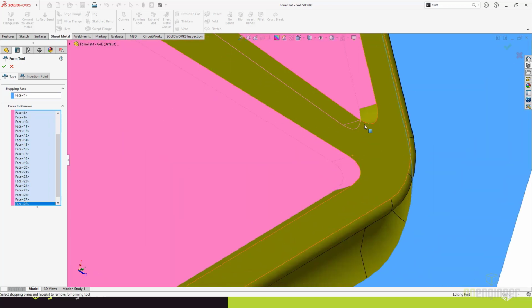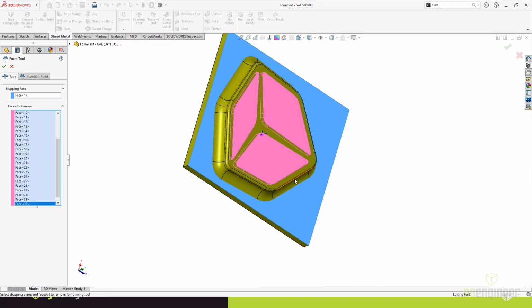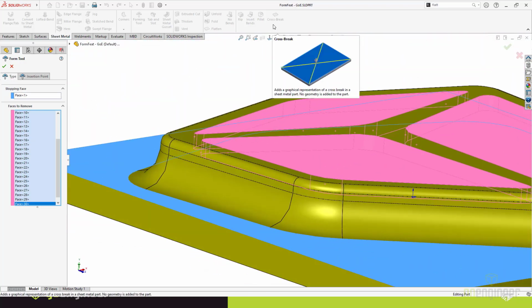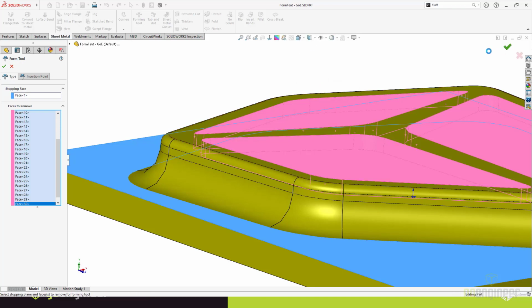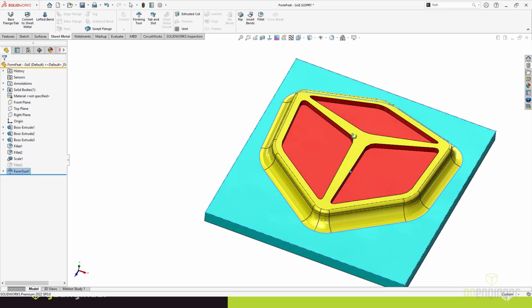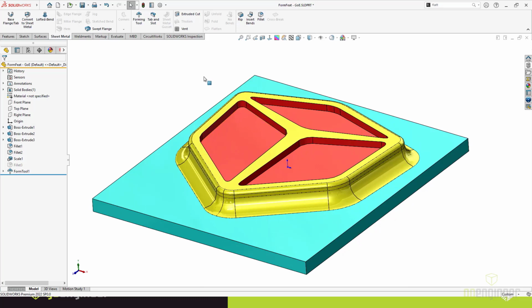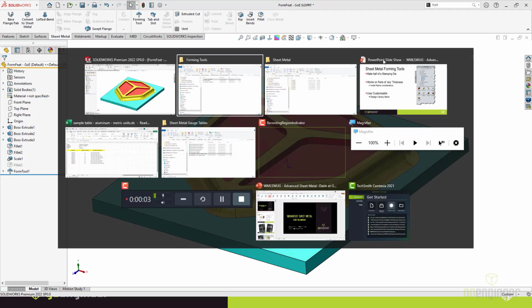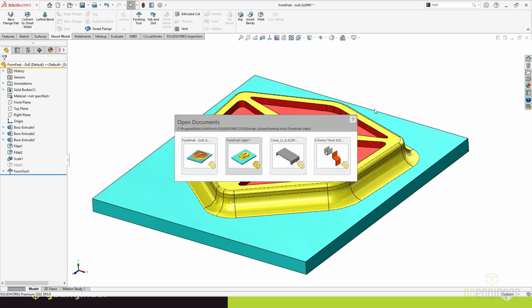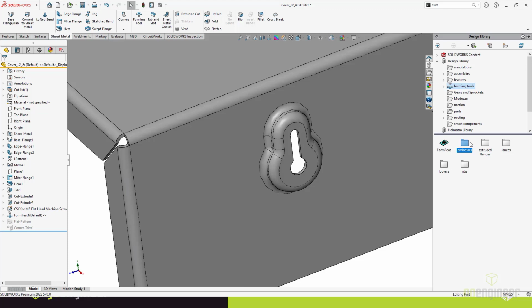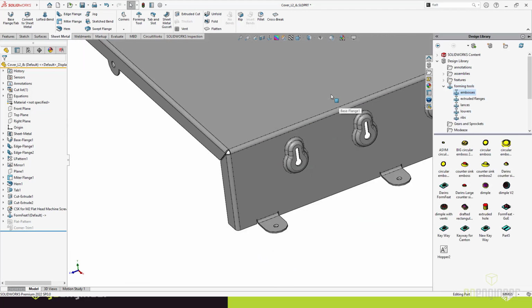Now geometrically, what's interesting about this is that the part you're looking at doesn't really have the geometry that would be necessary for that cut. There would be a protrusion that would have kind of a knife edge to it, and it would actually slice these areas out. But as far as this feature is concerned, it just has to be designated in this red 255, green, blue, 00 color in order for this to actually work. Now, once this is done like this, what you're basically doing is just dropping it onto the other component. And for this particular one here, we're just going to go ahead and drop that into a particular spot, and it will give us this embossment.